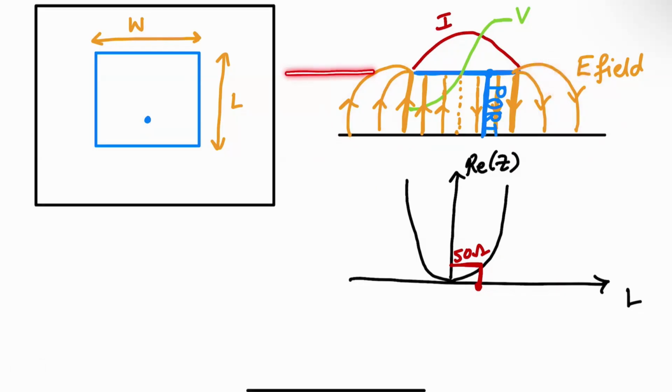So if I just take the top surface and I want to find the equivalent currents on that surface, we said that there is no electric current on this surface. You can associate an equivalent magnetic current on these two surfaces, which is essentially like saying that you have this electric field that's this way, right, coming from the fringing component, and that's the one that radiates. So if you look at it from above, what does it look like? And so I'm just going to erase this as well.